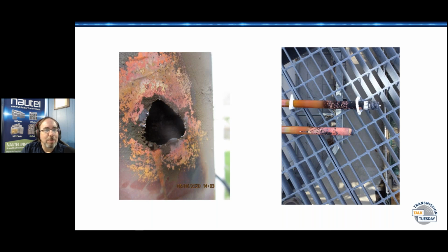Some of it's going to happen anyway, some of it's going to be lightning. But if you are out there doing regular hardware checks, doing temperature sweeps of coax and breakers, things like that, then those are the sorts of things that we really try to avoid. Not going to avoid it all. Again, if there's a lightning strike that burns a hole in a coax shield, for example, you're not going to stop that with maintenance.